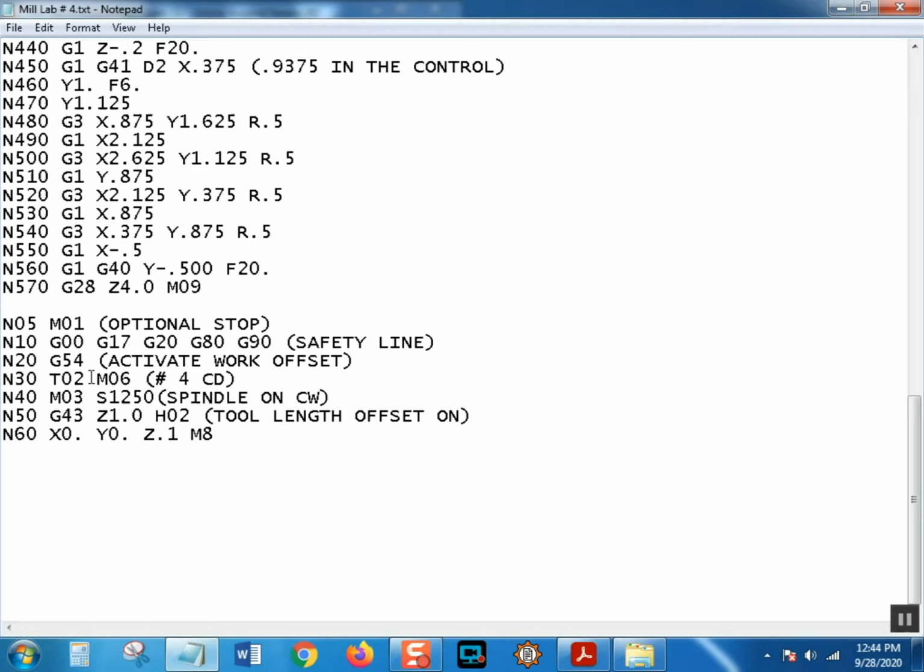All right. So you might want to copy all of that. Remember, you have to change, once again, your tool number, your H number. You're going to have to calculate your RPM up, which in this case you don't have to because I just told you what it was. Control S.